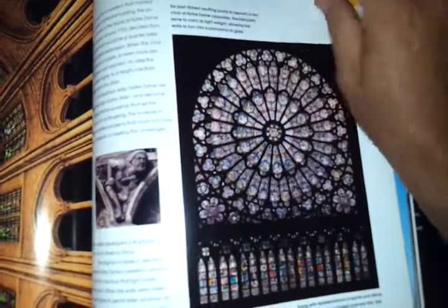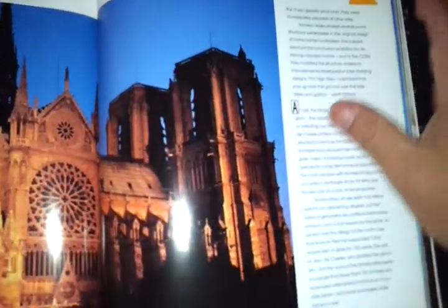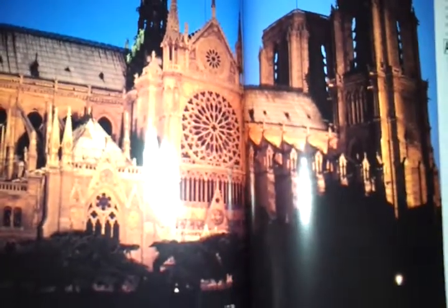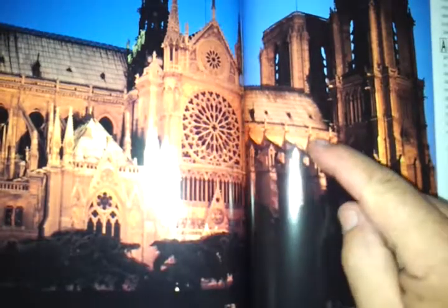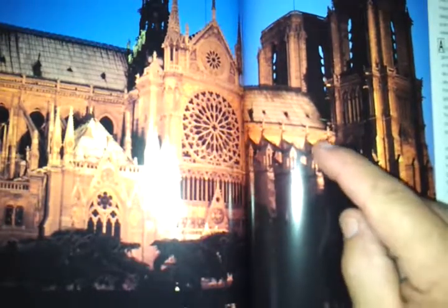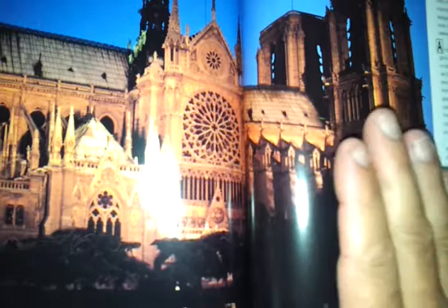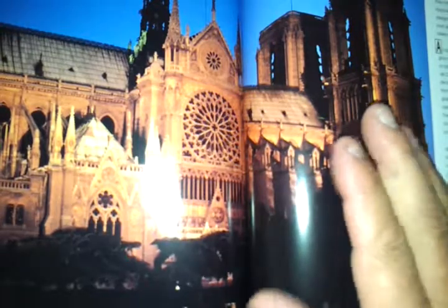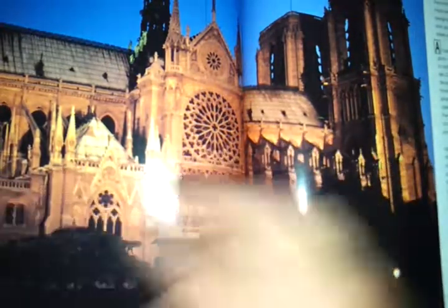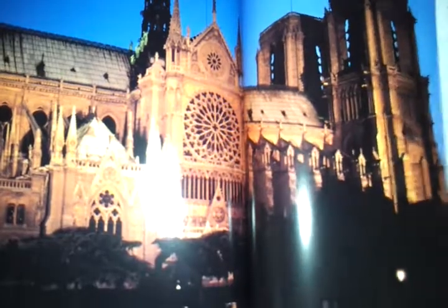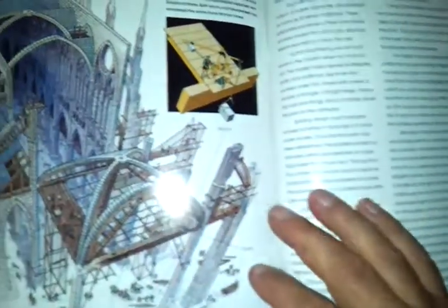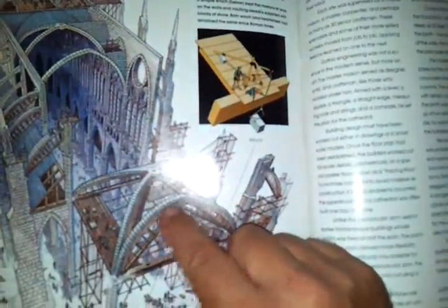Difficulty was, of course, that the large walls required support from the outside, and the support came in the form of these things called flying buttresses, which basically effectively created a very thick wall, but had lots of hollows in between the wall, created by these arches. So, you can see the construction of the cathedral over here. Again, all stone arches, everything in compression.